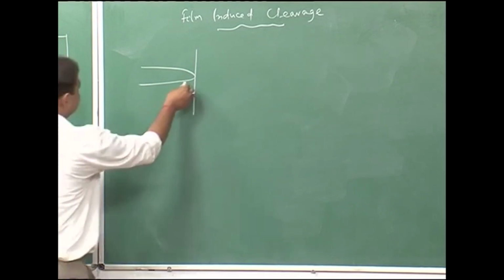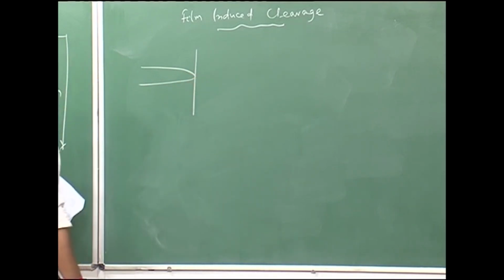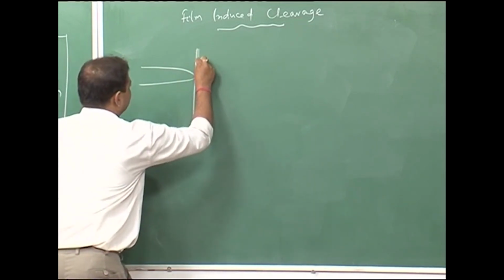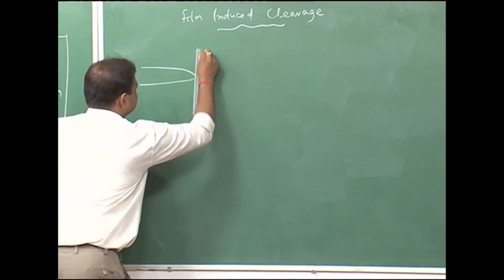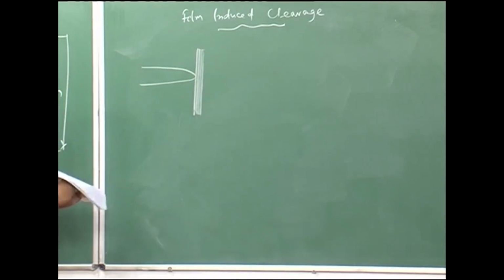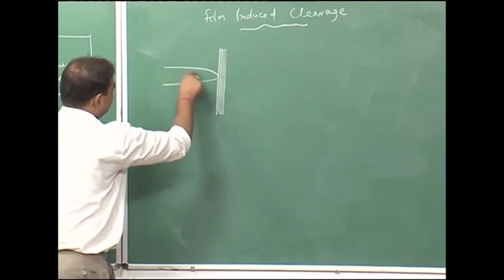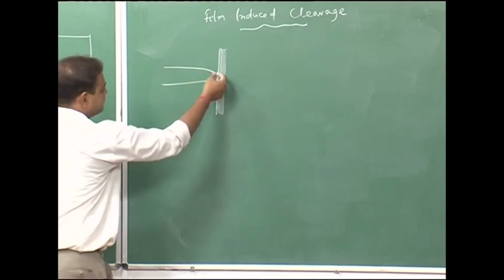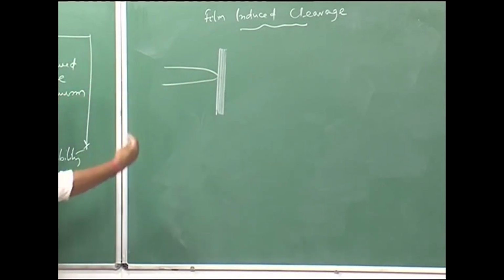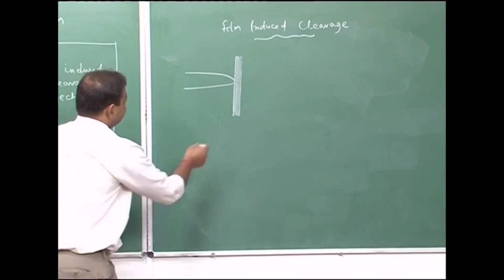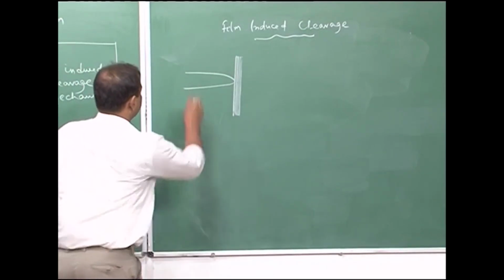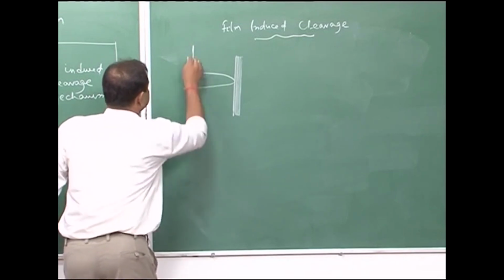Now, here we have dissolution, and that corrosion reaction leads to formation of a passive film. It is almost similar to tarnish rupture, but the salient difference in this case is that the film is forming at the crack tip, because the metal at the crack tip zone is exposed to the solution, and the corrosion reaction leads to the passive film formation, and this is under tension.